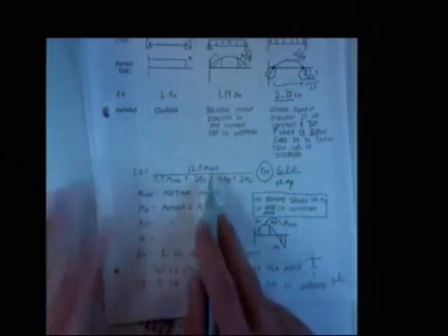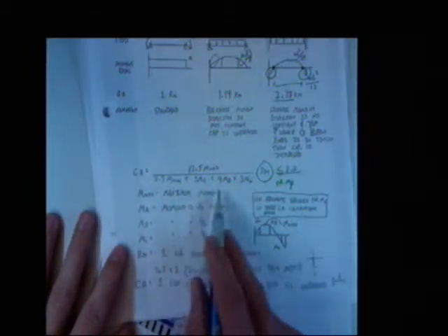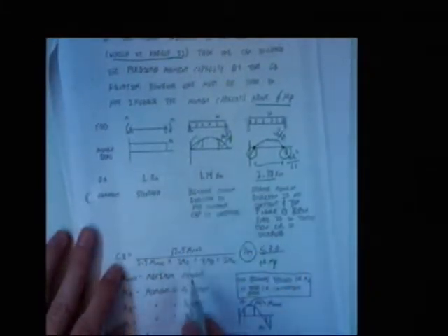Okay. Use the maximum moments, the moment at the quarter point, the half point, and the three-quarter point. You plug into this value, and the more curvy something is, the higher the number should be. That's the most common C sub B, and you apply it between the braces. And then we have 2 other C sub B's. And what are they for?